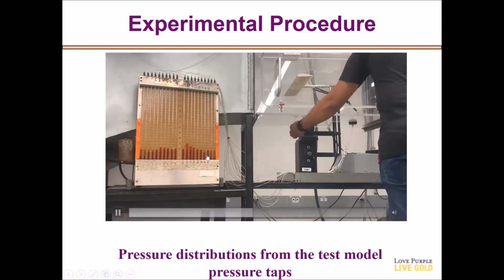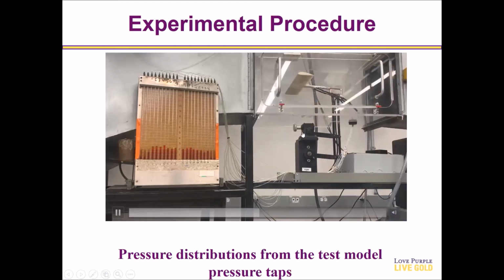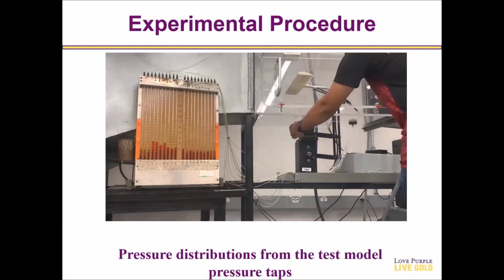As mentioned earlier, the right hand side basically focuses on the bottom surface of the airfoil, and as we are increasing the angle of attack, you can see there has been some change on the left side, which corresponds to the top surface of the airfoil.